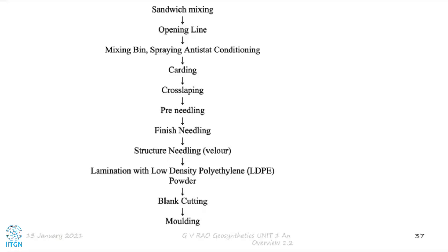If you really see carefully the bags which you are getting, not cement bags, the wheat bags and all, open them up and you find that outside, I told you, it is a slit film tape kind of woven material, but inside there's a thin layer sometimes. The thin layer is LDPE or LLDPE, low density or linear low density polyethylene, which is coated so that the material doesn't come out, the atta doesn't come out. So the good bags have got that, and then the rest of it will follow.